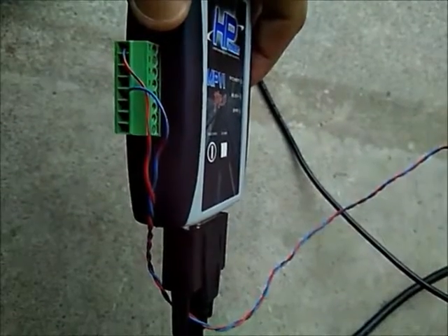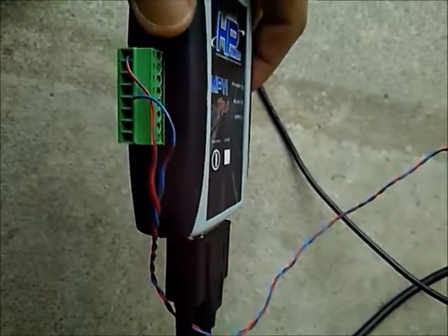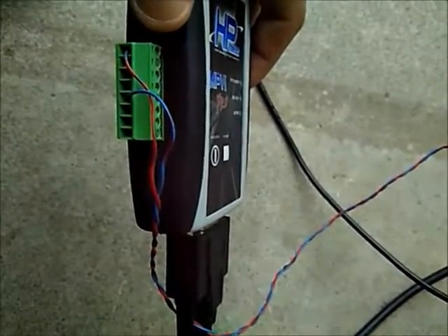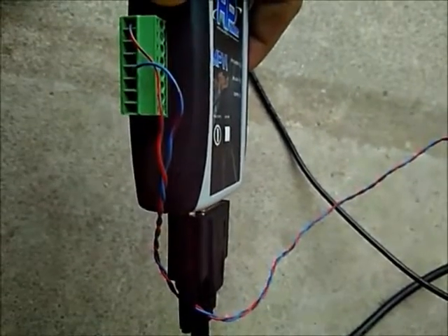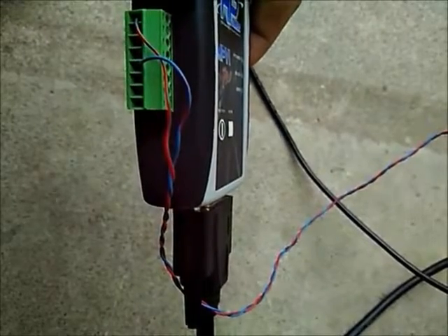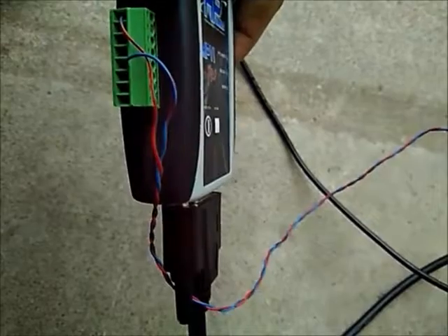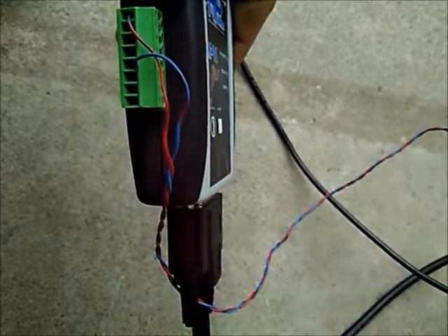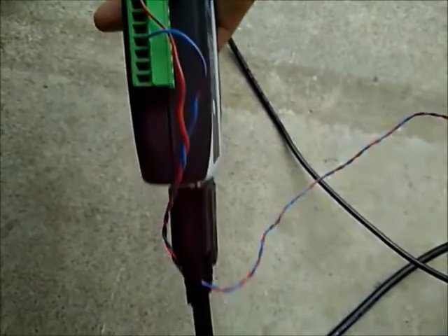Piece of advice I would say is just to use some kind of shielding if you can for your wire. I mean, twisted pair is what I'm using here. You can see the twists in it, and twisted pair is good for canceling out magnetic interference. Like if you've got high power noise from something that's using a lot of current nearby, and cars are very noisy, right?